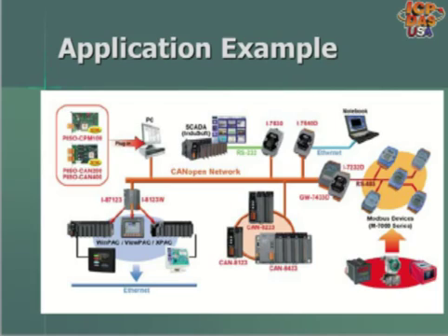PAC controllers like WinPAC, ViewPAC, and XPAC can use CAN communication cartridge modules like I8123W to add CAN communication. CAN I/O racks support a wide range of analog and digital I/O cartridges for use in CAN networks.